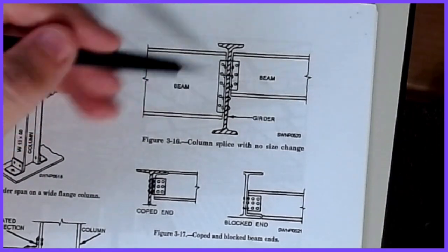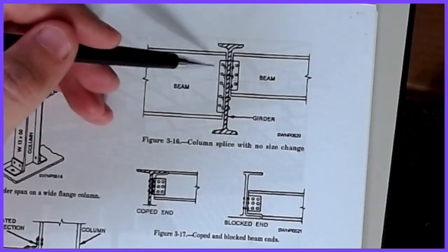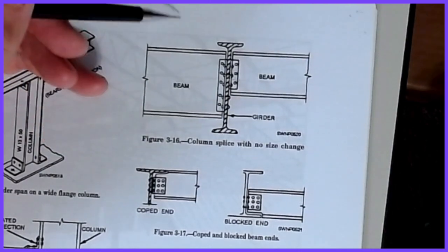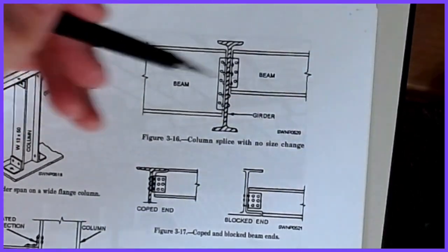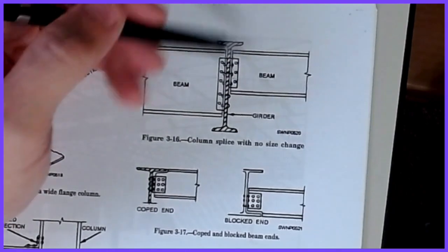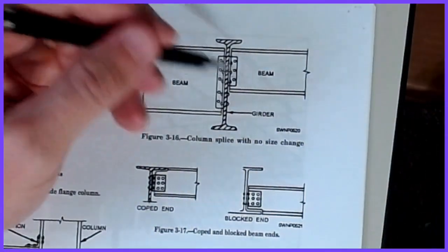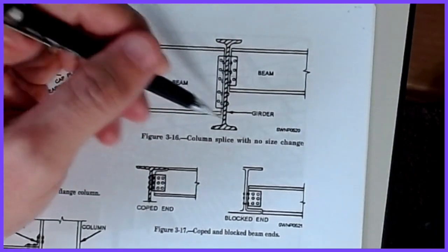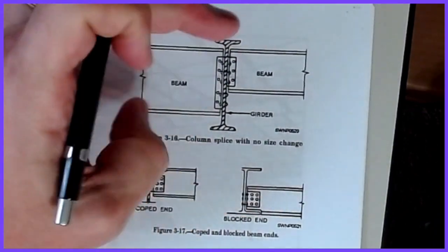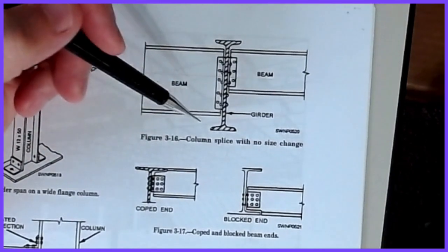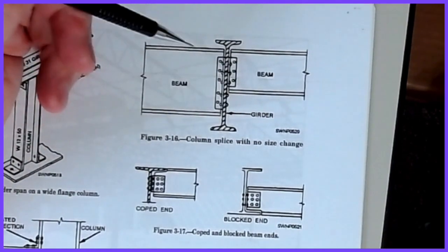Generally you want to be careful about this as well, because depending on the loads, this can cause a torsional effect in the girder. If you need a big beam, chances are you have big loads. Whereas if you have a smaller beam over on this side, and these are unbalanced, this girder wants to turn, in this case probably rotating counterclockwise a little bit. Not all the way, but that would be a factor you would have to look into in the design of your girder.